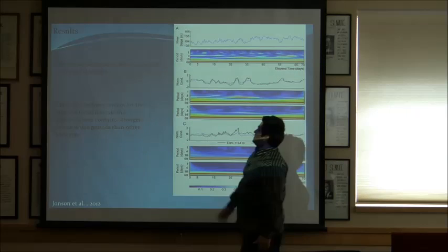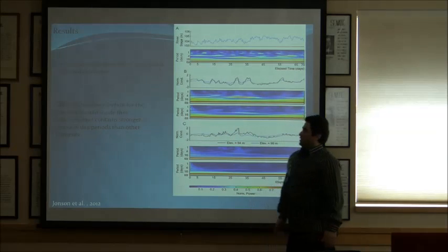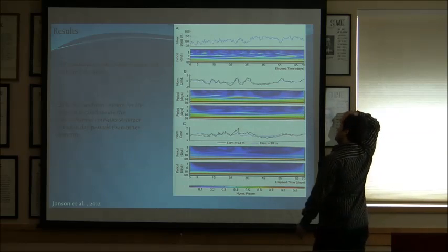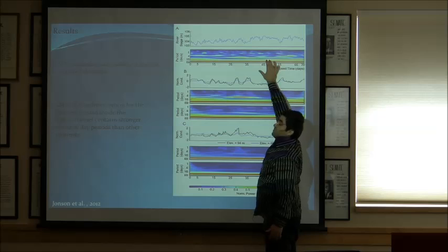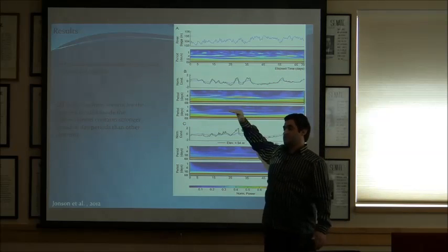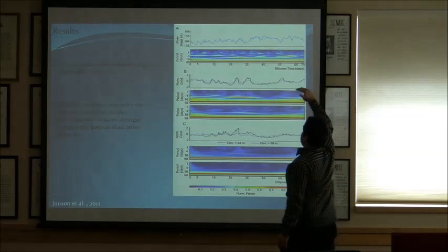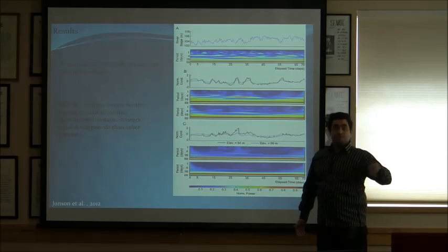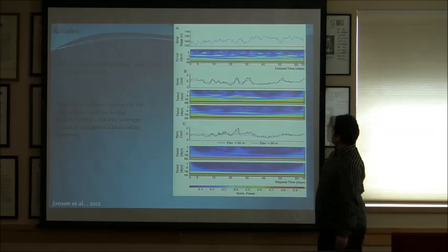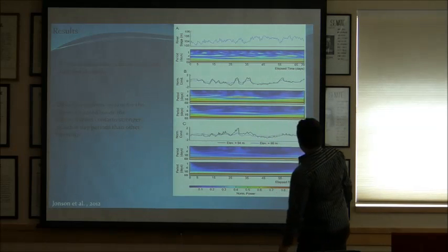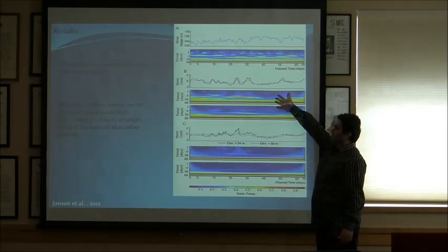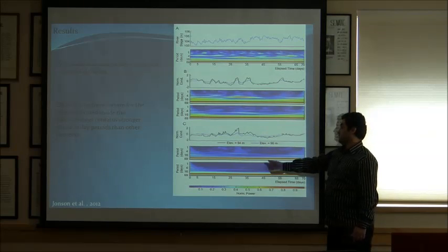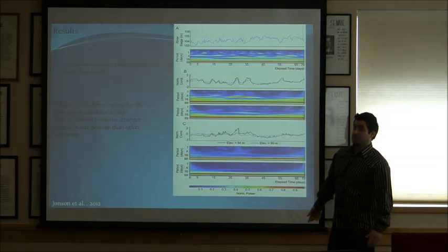Okay, so in order to process the data, we used a time-frequency analysis tool called the S-transform. So we do the time-frequency analysis of the stage data, and you notice the dominant periods on this stage data, and you notice the dominant period at each element of the 3D model. Here, this element was assumed to be inside the valley channel. This element was assumed to be outside the valley channel region.